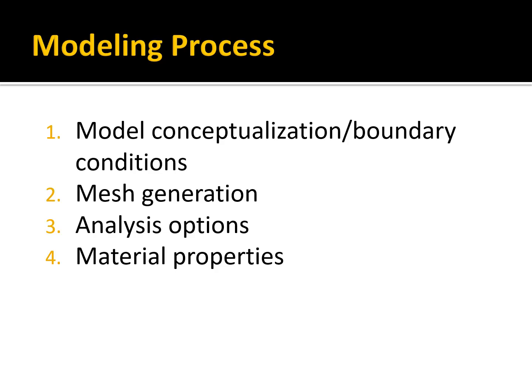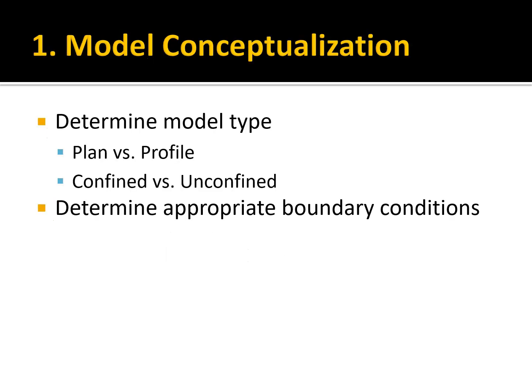All right, the modeling process generally has 4 steps. Before you build the model, you do model conceptualization, determine your boundary conditions, then you build your finite element mesh, select your analysis options and your material properties. So we'll talk briefly about each of those in these slides.